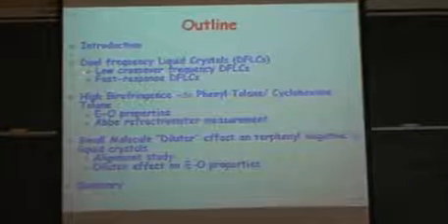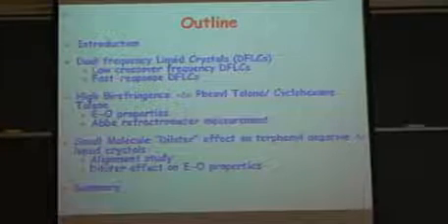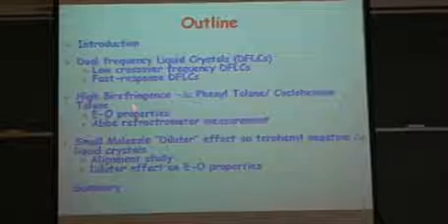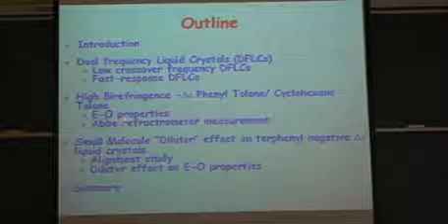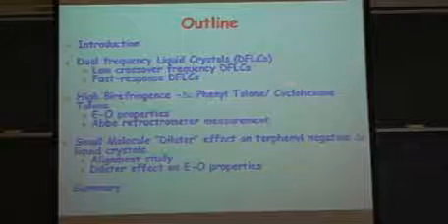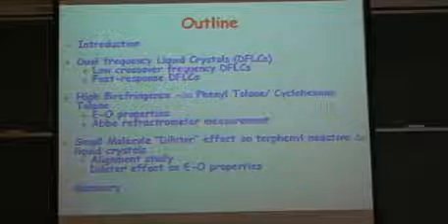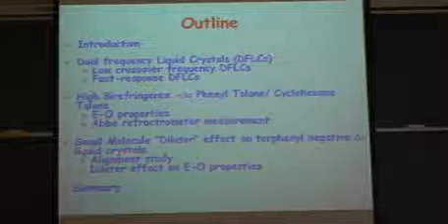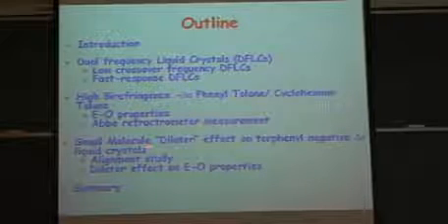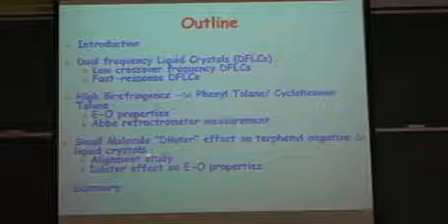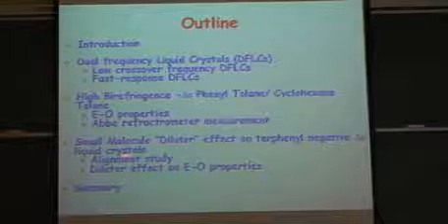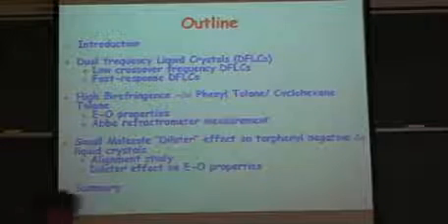First is a special faster response time mode, dual frequency liquid crystal. And then from the material side, I will talk first about high birefringence liquid crystal, such as to enable thin cell gap. And then third, I will talk about the small molecule diluter effect on negative dielectric anisotropy liquid crystals. And finally, I will give the summary.